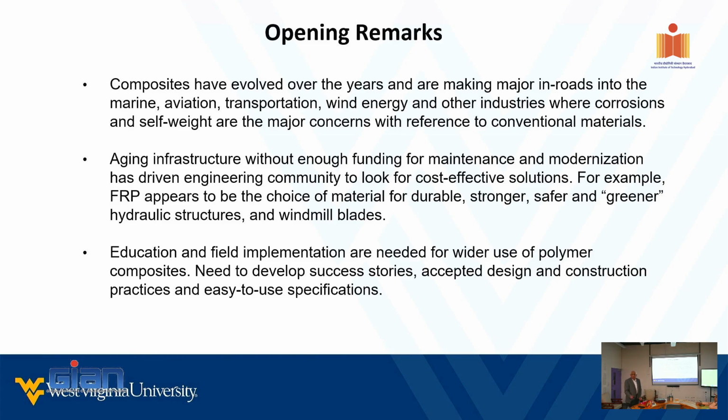All these fabrics that I'm circulating, all these have different grades. Remember, when we talk about glass composite, we have E glass, AR glass, S glass, like that. So they all have certain different properties. And the second thing, when you talk about carbon, I have carbons that have 5 million psi stiffness all the way up to 500 million psi stiffness. So obviously the costs are going to go up. Perhaps they go up in a geometric proportion, the cost from the standpoint of the stiffness.